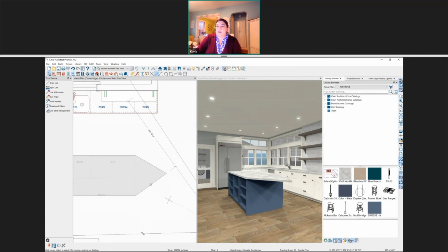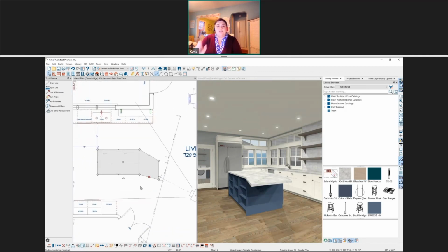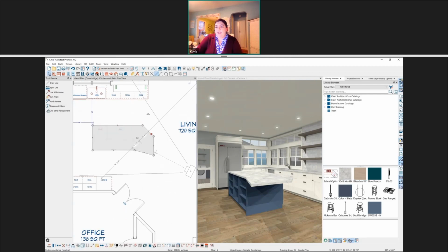And when I create another break and pull out this diamond again, now I have a 6-sided object, and I can now manipulate it into its correct position. So I'm going to grab this edge and just pull it out a little bit. And I'm going to use some tools that we have in the edit toolbar to make this line and this line parallel with this wall.